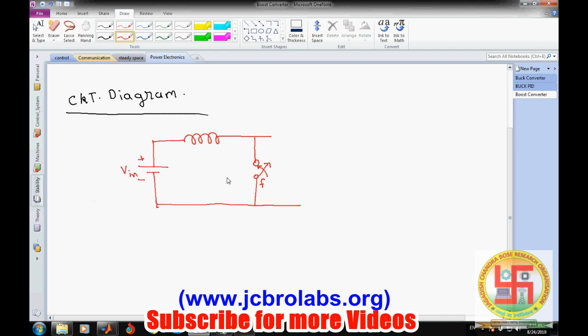And then we have a freewheeling diode here, and then there is a capacitor at the output in order to remove the ripples in the output voltage. Okay, and here we will get the output voltage VL, right? So here it is C, so we can denote the current going through these, and here it is the inductor current IL, and this is plus minus voltage across it.